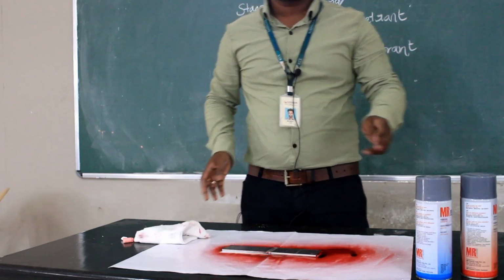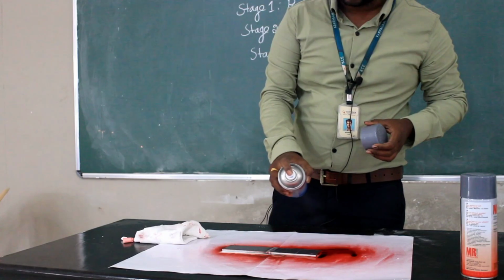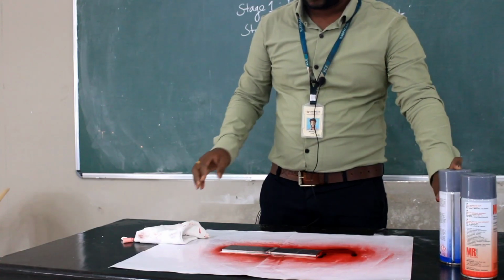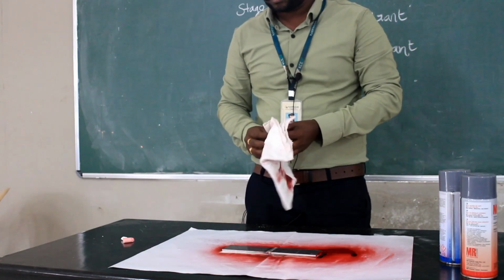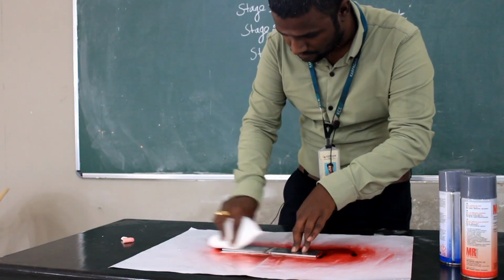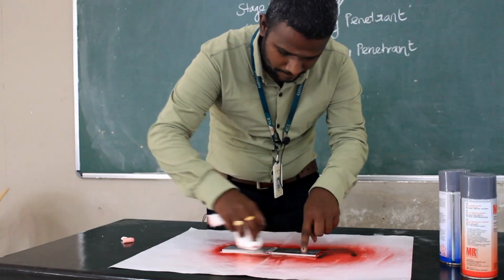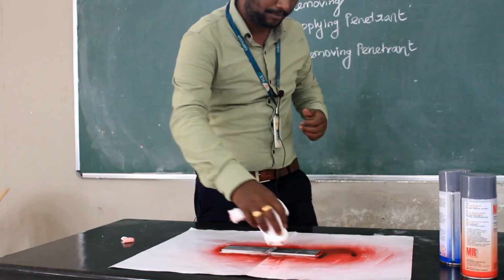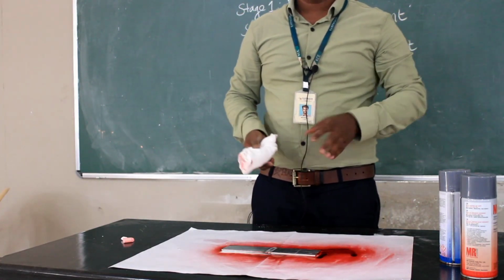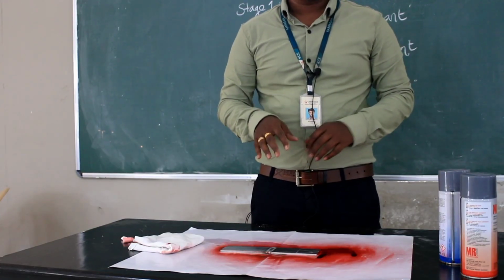After that, as already told, I have to apply another remover for removing more of the penetrant. So I am applying the remover so that I can remove all the penetrant. Now stage 3 is completed, and we have to wait for a minute for the remover to work.